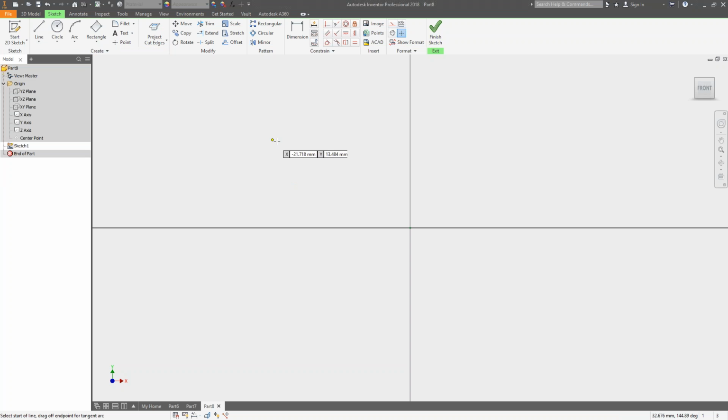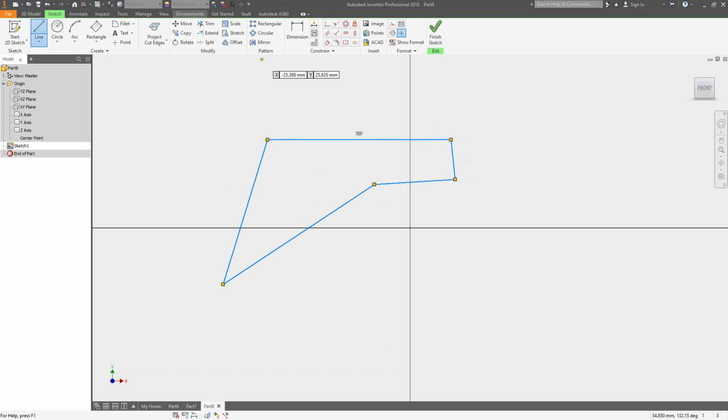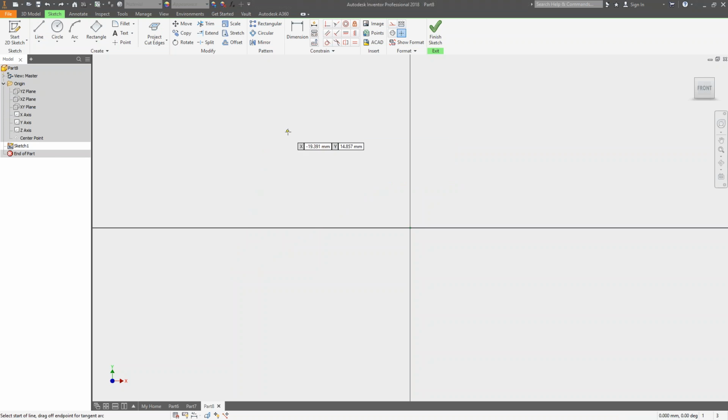So let's say I want to draw a relatively complicated curved component that has combinations of straight edges and curved edges. When I'm in the line command, I'm going to just pick a point to start, pick a point to end. Here's another tip. I gave this one a few weeks ago, but it's called dimensioning as you go. So you see that dimension of 26 whatever millimeters, rather than just drawing this and going back and dimensioning it later, which is okay, but the better way to do this is when you are sketching your line. If I know this line is going to be 20 millimeters, just type in 20 and hit enter.